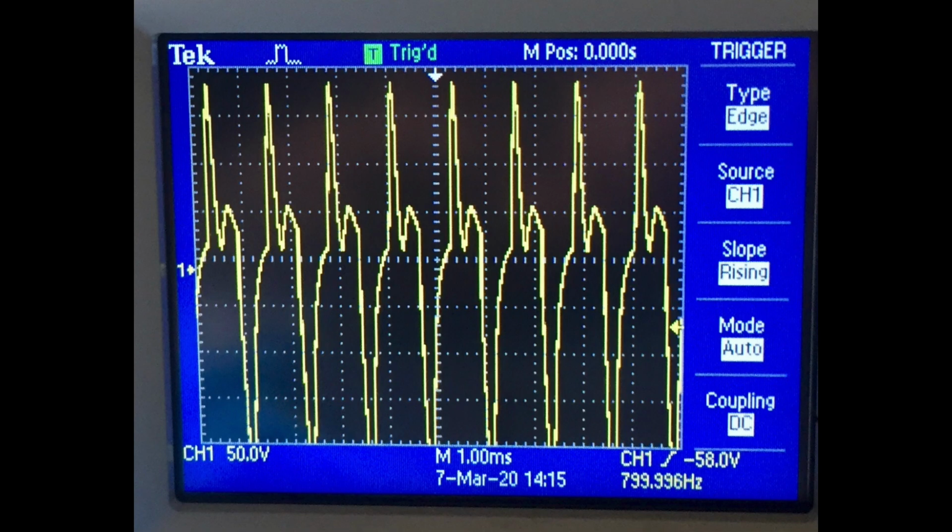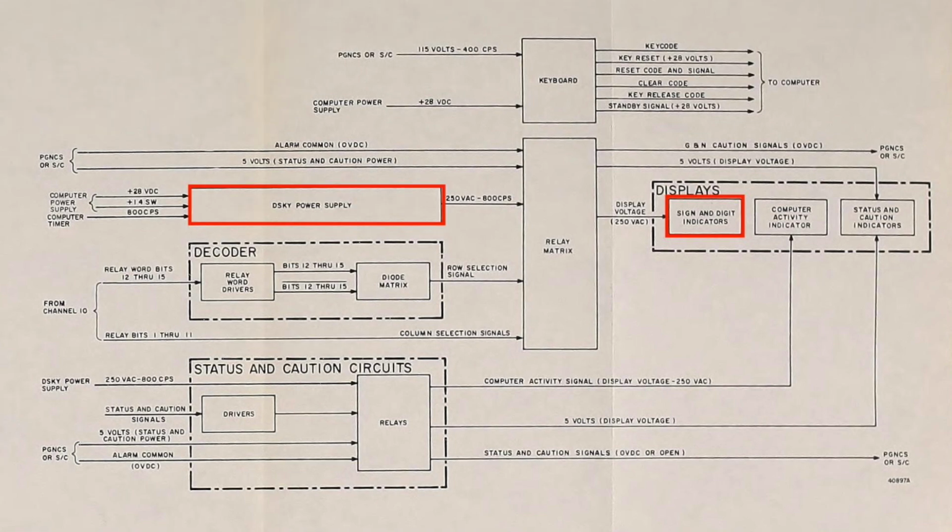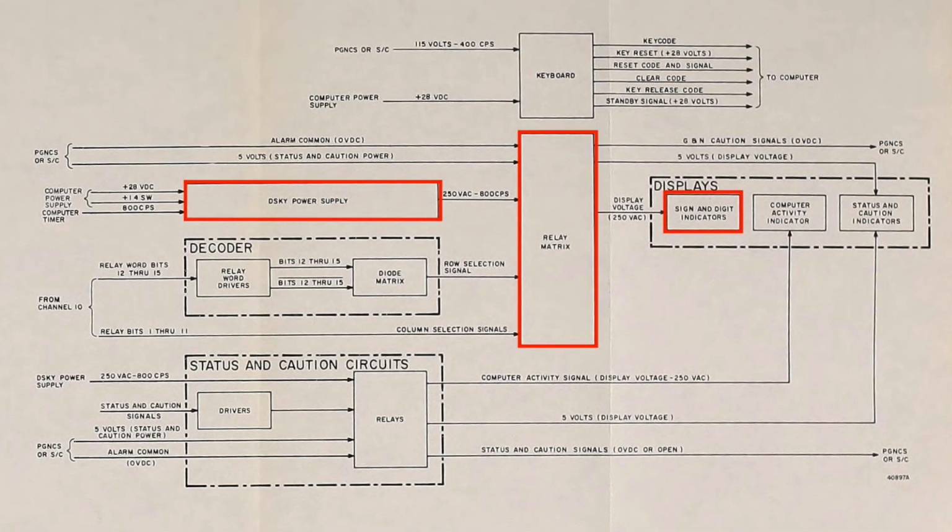Unfortunately, when Carl checked the supply, he observed that it was a bit short of spec. The spikes are fine, actually the spikier the better for EL displays, but the positive side is a bit weak. Nevertheless, Carl was able to obtain enough voltage by overdriving it a little bit, and we considered it good to go. So we're doing pretty good. We have the display, we have the power supply, and now to connect it the same way that they did